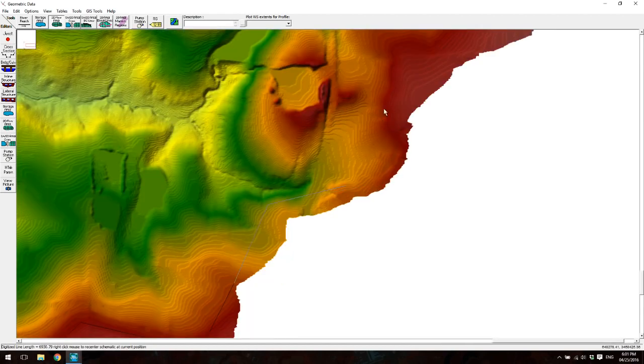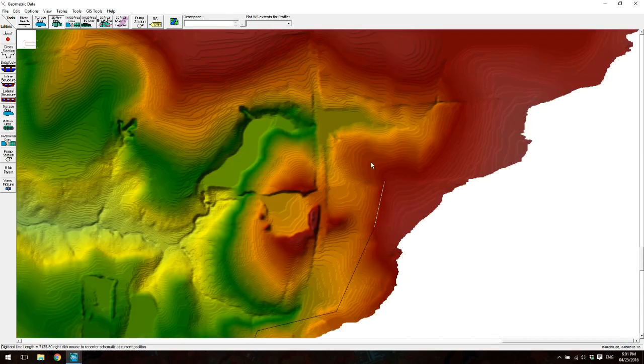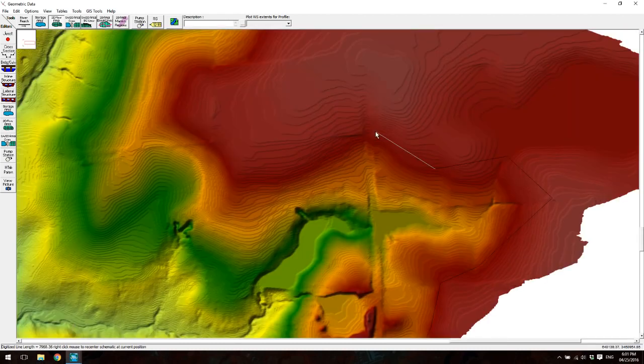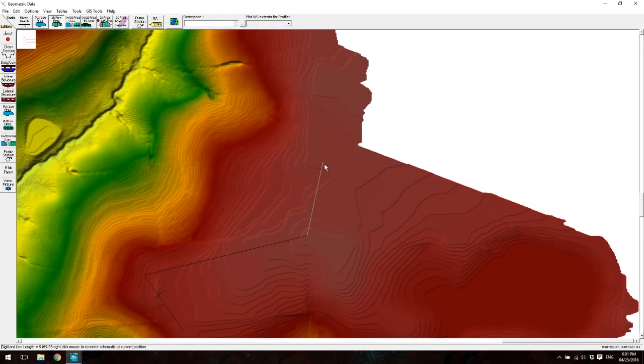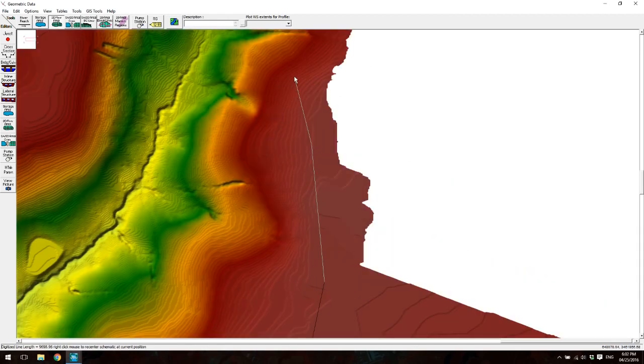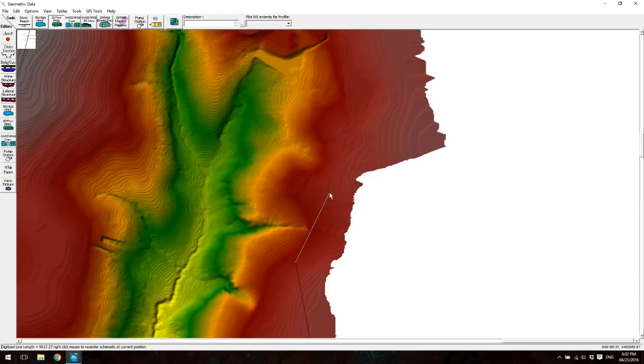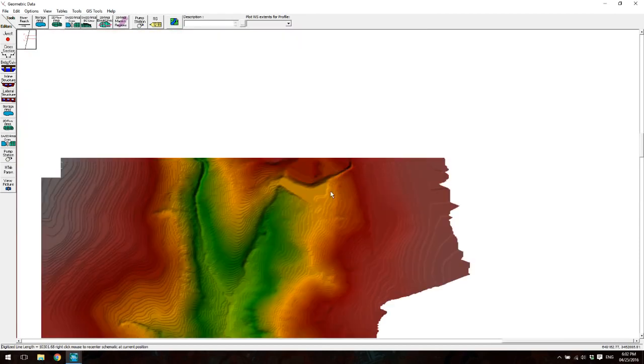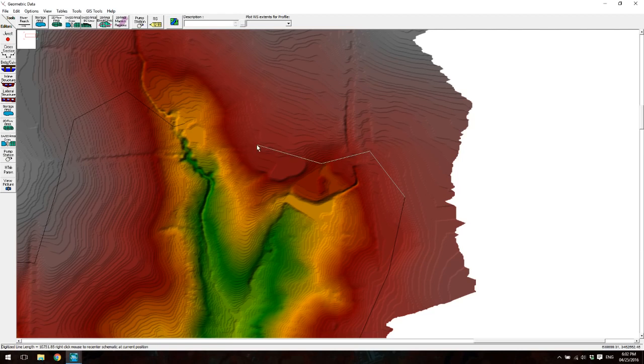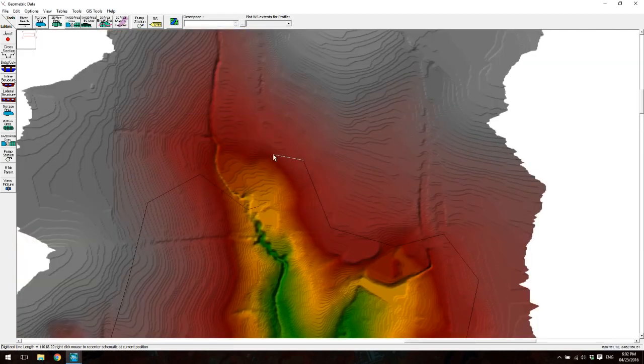Okay. You can create a 2D flow area based on your computer resources. For example, if you have a faster computer with a good processor, you can give a bigger area. Also, it depends on the flow rates that you want to give.